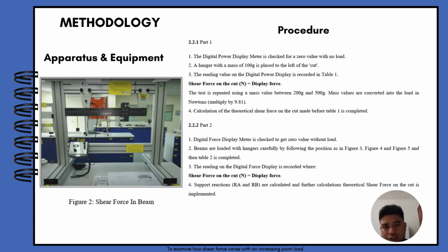For the second part, we follow: one, the digital force display meter is checked for zero value with no loads. Second, the beam is loaded with the hanger carefully, following the positions in figure 3, figure 4 and figure 5, and table 2 is completed. Third, the reading on the digital force display is recorded as the shear force on the cut in newtons as display force. For the support reactions, reaction A and reaction B are calculated, and further calculation of the theoretical shear force on the cut is